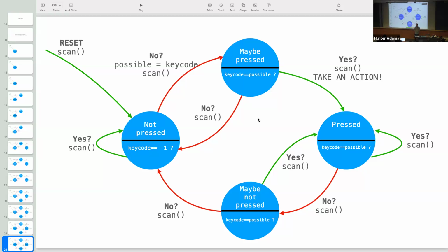But it's an absolutely correct observation that the first step of implementing something like this is characterizing the button, scoping it, pushing the button, and seeing what my bounce rate is, so that you're timing a software solution to this debouncing problem so that you are debouncing at a rate that is appropriate for the rate at which the button's bouncing. In this case, I can assure you that we are. You could check this yourself on the scope.